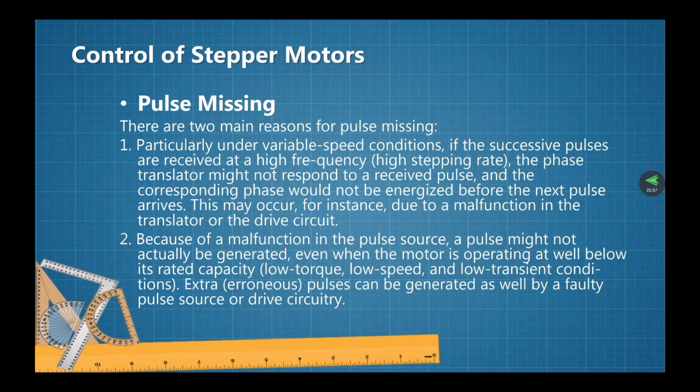Consequently, it is not known whether a significant error is present, for example, due to a missed pulse. If a pulse is missed by the motor, the response has to catch up somehow by a subsequent overshoot in motion, or else an erratic behavior may result, causing the rotor to oscillate and probably stall eventually.